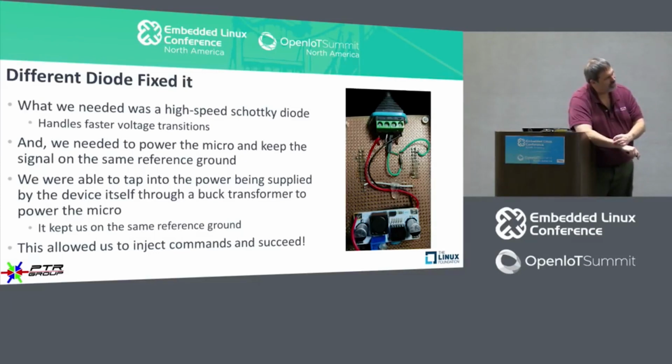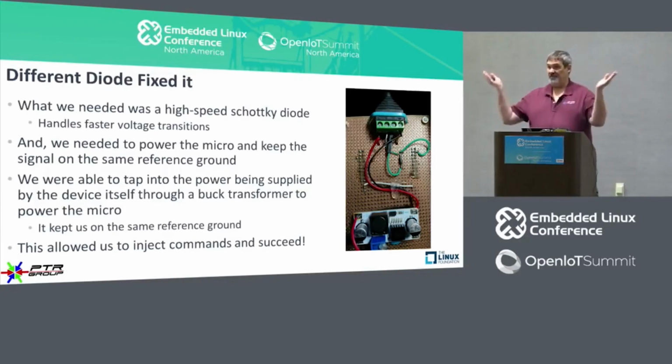We could actually inject new commands and watch what happens. As we were going through doing the decode on the protocol, we actually found out that there was some places where it was representing 100%. So you would see 100% on one thing or 100% on the other thing, and then the mix of 100%. So you would end up with 100% if you added the two of them together. Those were both being represented in 2 bytes for each one of those values.